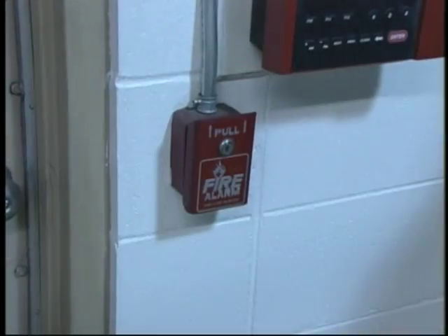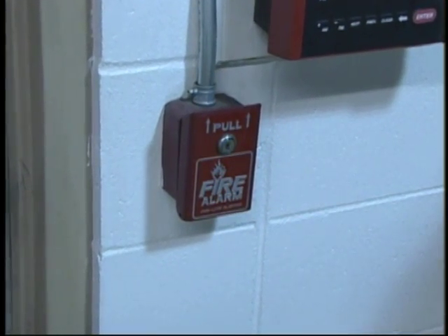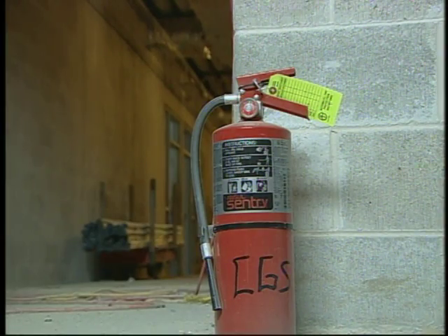Someday it could happen. There could be a fire, and you might be the first one to see it. Will you know what to do? At your job site, there's a firefighting program that's been prepared for all phases of construction and demolition work. Be ready ahead of time for your part of the program by knowing where alarms are and when to use them, and where fire extinguishers are located and how to use them.